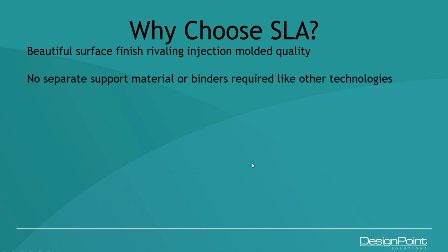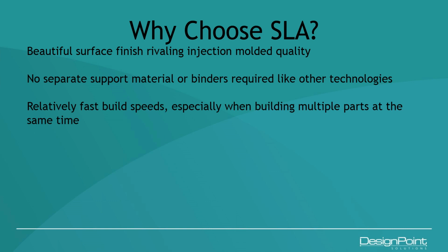You don't need any separate support material or binders required like other technologies. When there are supports, it's made from the same exact material. Those supports, the computer creates these little standoffs for supports. Those are literally wiped off during the cleaning process. It has relatively fast build speeds, especially when building multiple parts at the same time. It also has a very simple post-processing that requires minimal skill.